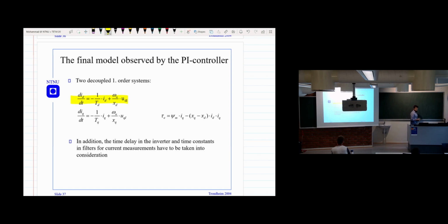And for these two first-order equations, if you remember this machine, we have one field current controller. This is the field, and one is the armature. This one I can say is If for the DC machine. And the armature one we are using to control the torque.